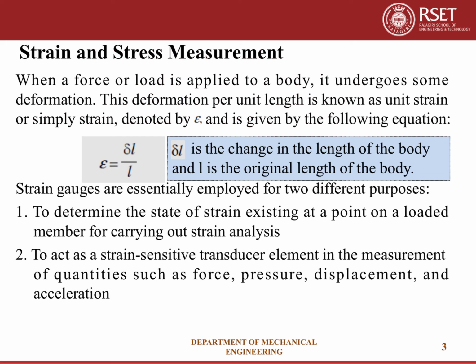And also we have a relationship between strain and stress and Young's modulus. So Young's modulus is equal to stress by strain. So by knowing the strain, we can calculate the stress. So here in this lecture, we give importance to strain measurement, and as we know, once we could measure strain, it can be used for measurement of stress.